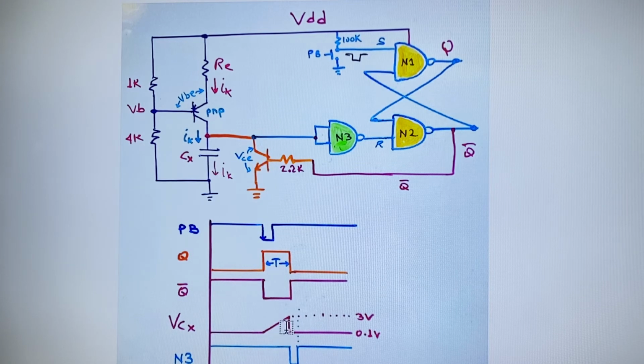That's why the capacitor is right there, discharged from 3 volts to 0 volts. I always say 0.1 or 0.01 because there is a voltage drop from collector to emitter, so it is not ideally equal to 0, but in the real world it is equal to 0.1, the VCE. So you might consider 0.1 if you wish in the equation.